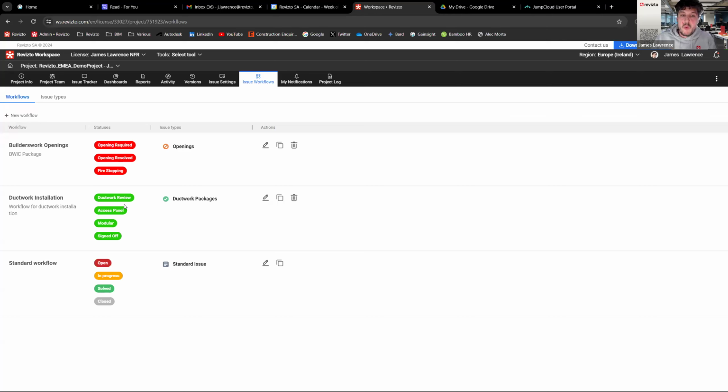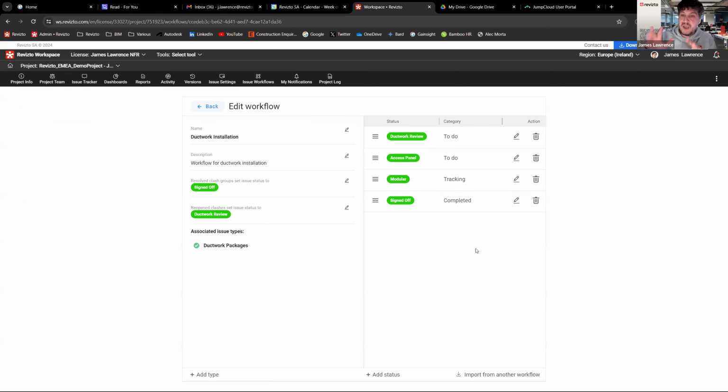The one that I'm going to kind of open up and have a look at today is the ductwork installation. So if I open up the ductwork installation and go to edit, you will see what the workflow looks like. So we have a name, we have a description. Resolved will be set to signed off, and opened will be set to ductwork review in terms of clashes. Now, I'm not saying I'm going to be using clashes with this. It's there as almost like a buffer. So I went through and created custom statuses.